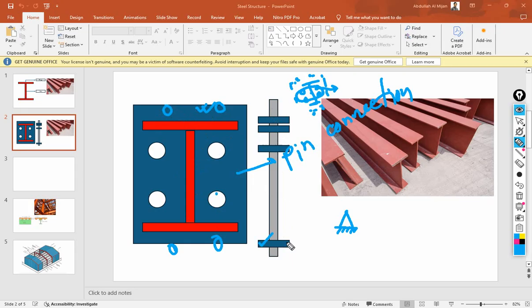We provide an additional nut for making friction with the concrete column. And here is the top part of this anchor bolt. This free end will always be kept free for safety purposes, and in this gap a steel base plate is substituted.